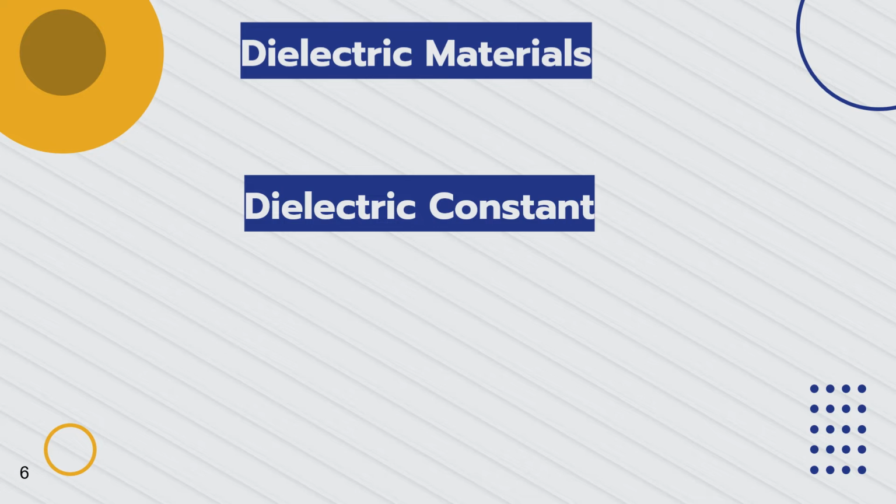In more practical terms, it represents the ability of a material to store electrical energy in the presence of an electrical field. All materials, including vacuum, store energy when placed in an electric field. The permittivity of vacuum is defined as the physical constant epsilon 0, which is approximately 8.854 times 10 to the minus 12 farads per meter. This constant appears in many electromagnetism formulas.